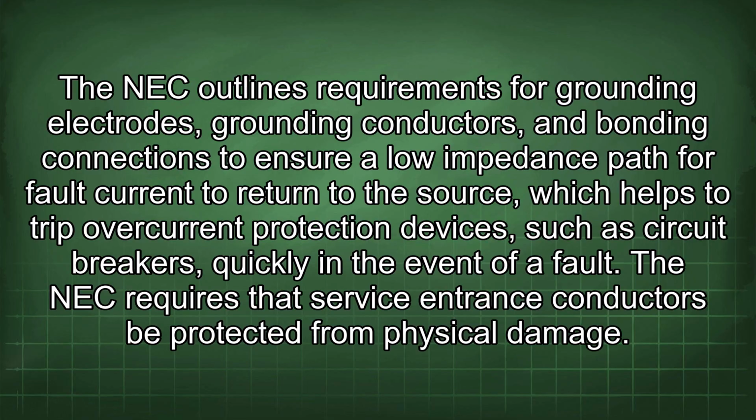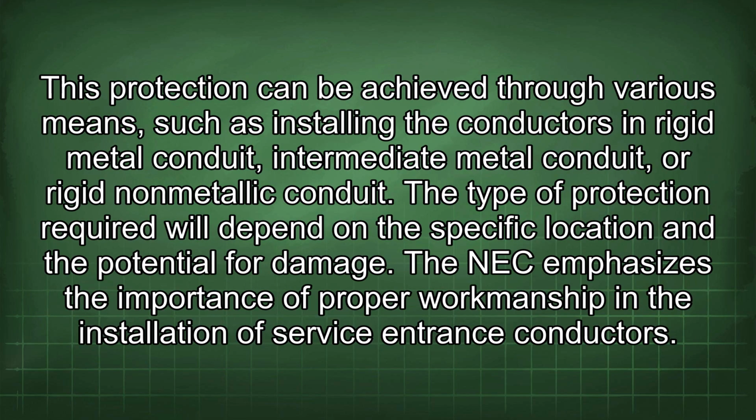The NEC requires that service entrance conductors be protected from physical damage. This protection can be achieved through various means, such as installing the conductors in rigid metal conduit, intermediate metal conduit, or rigid non-metallic conduit. The type of protection required will depend on the specific location and the potential for damage.